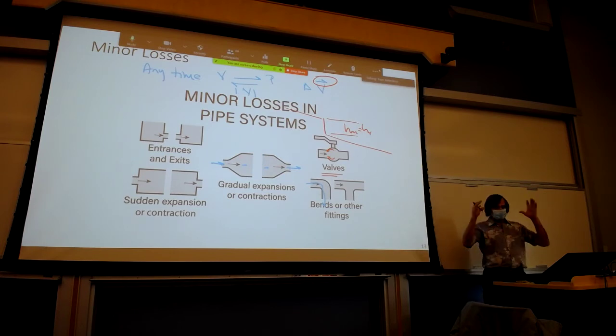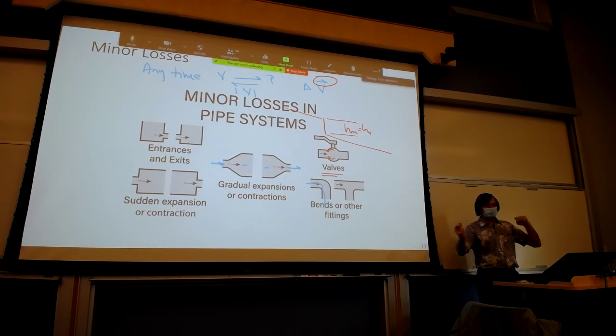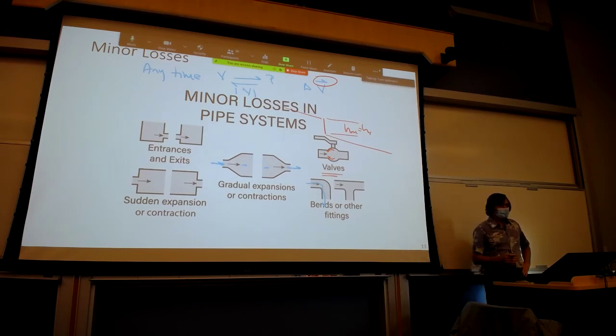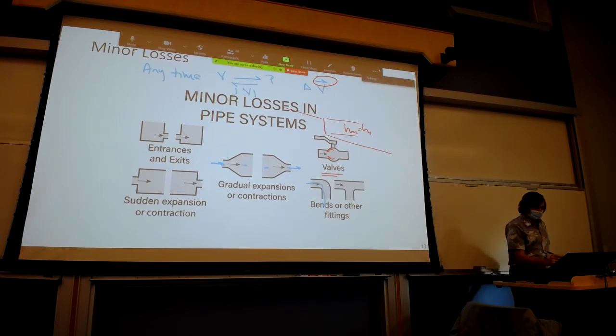When we calculate the energy loss just due to a feature like this, it includes the frictional resistance as well as the inefficiency of converting from velocity to pressure, as well as the increased turbulence if you're changing the direction of the velocity vector. So you don't have to calculate a friction loss within a feature where we have minor losses.